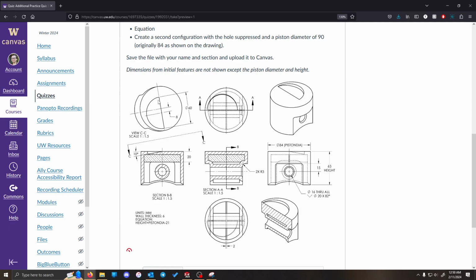Similarly, we have the little cutout on the top of our object. We can see that it cuts into our object, but the shell thickness remains consistent before and after, and only changes in thickness within that cut. That tells me that this cut is going to need to happen after the shell, because if it happens before the shell, then it's going to have material following along on the outside. We'll have an indent on the inside.